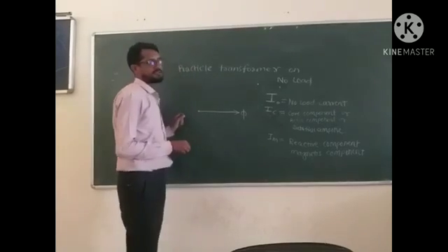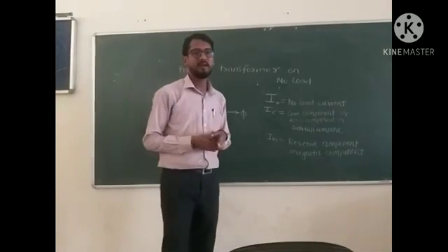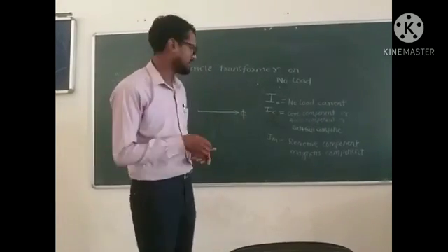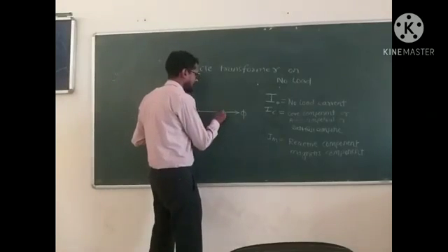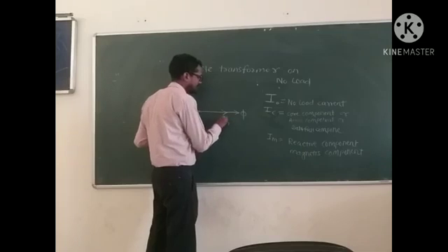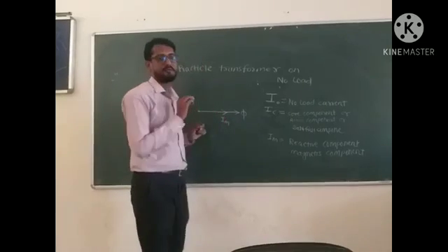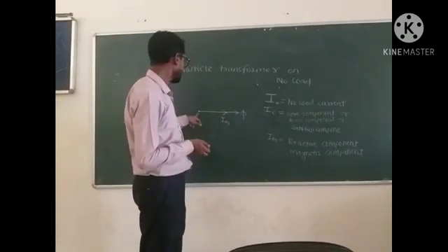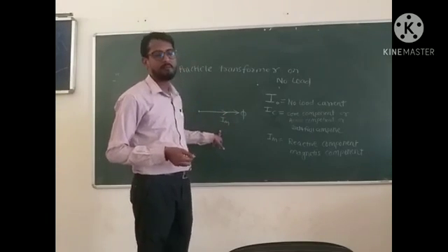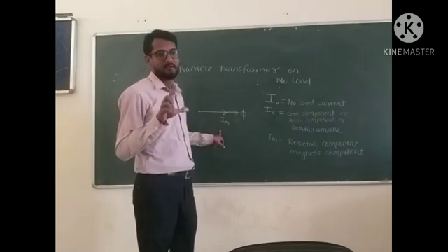We know that the flux phi is always in phase with the magnetizing component. That means flux phi and the magnetizing current Im are in the same phase.